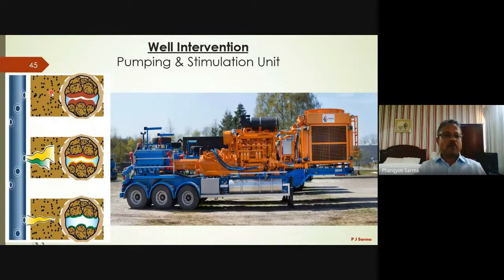Now, if these pore spaces are partially or totally blocked with scales, these scales need to be removed. With stimulation, by pumping the right kind of treatment fluid, maybe acid, maybe scale squeeze treatment, we remove this and clear it.